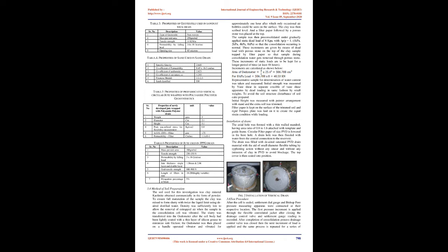In the present investigation, it is intended to use sand, sawdust wick, jute, and polyamide polyester geosynthetics to fabricate the vertical geodrains of different diameters in relation to the diameter of the hydraulically pressurized oedometer, Rowe type, which has special facility for measuring pore pressure and settlement during consolidation due to radial flow of water. The present investigation will compare the theoretical values of degree of consolidation with experimental values for all n values, where n equals the radius of the oedometer to the radius of the drain.